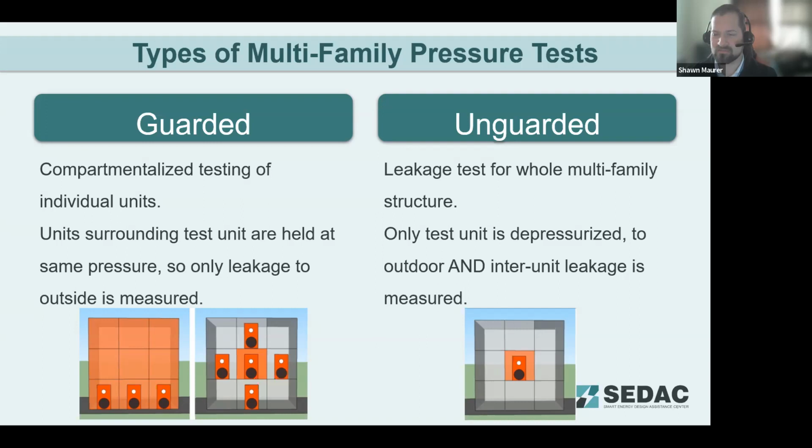One of the side benefits of requiring an unguarded test is that in multifamily buildings and even in commercial structures, it allows builders to also check if fire stopping is properly installed, as these materials are also closely aligned with the proper air barrier alignment. So if you've got a large opening in a partition, that's also a fire penetration that needs to be addressed.